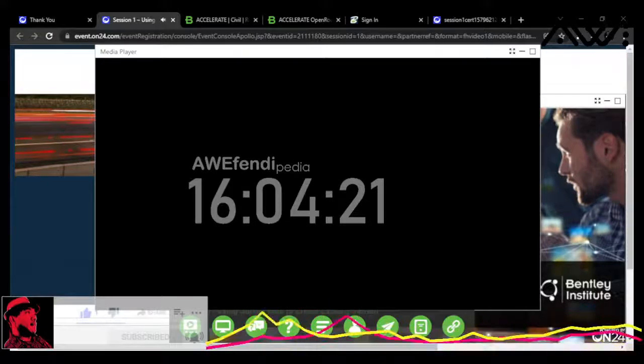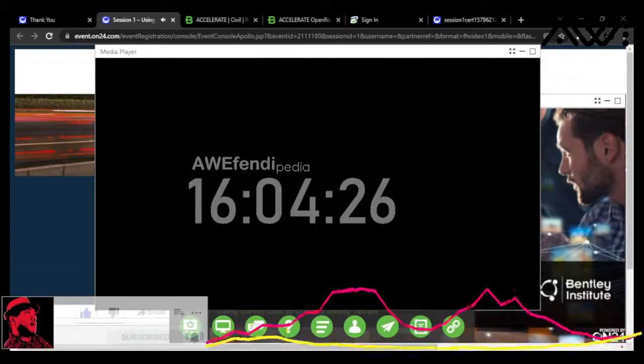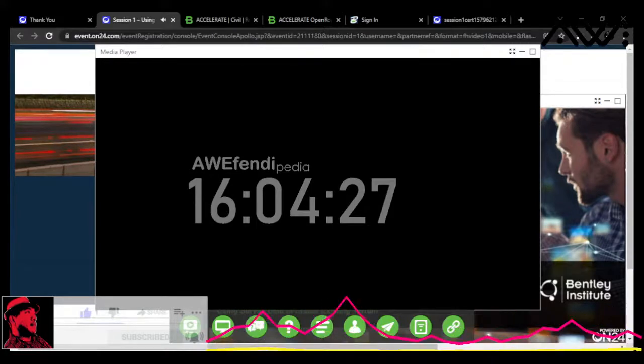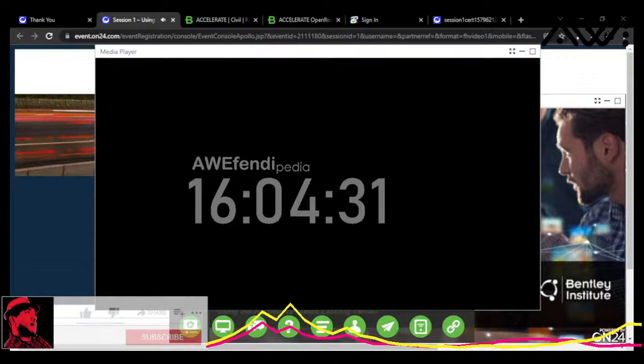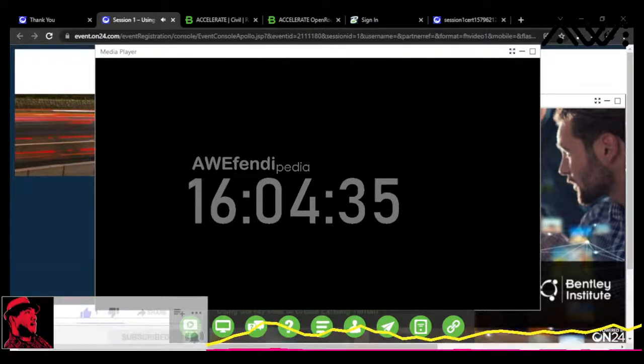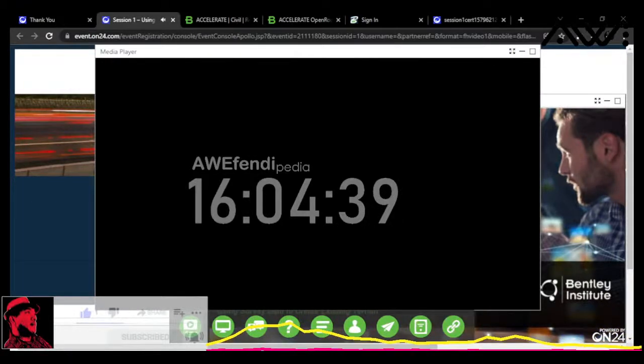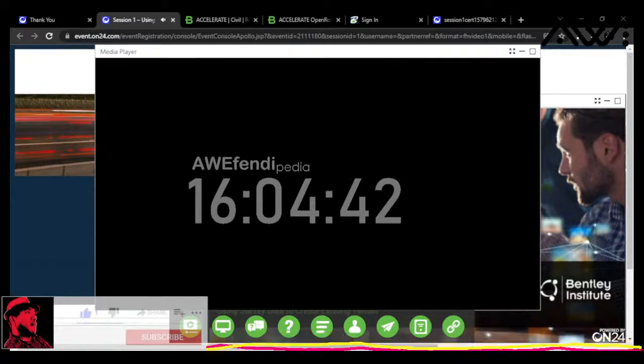I'm going to hit apply, and it's going to bring in those points. It's going to go and look for the feature definitions that match the alpha code, and then I have to do a fit here so that I can fit in where our project is. And my points have come in. If I zoom in on them, I can see that a feature definition has been assigned, and the feature definition told it to place this cell for the point. So I have some control points there now.